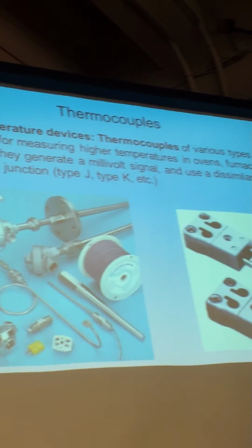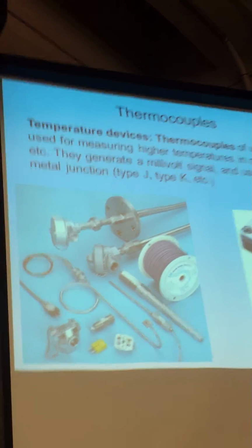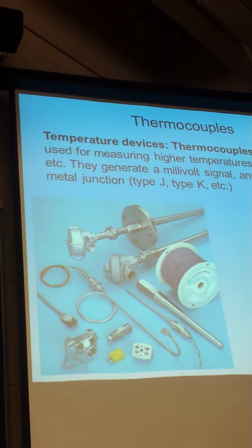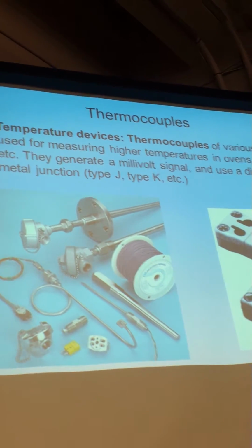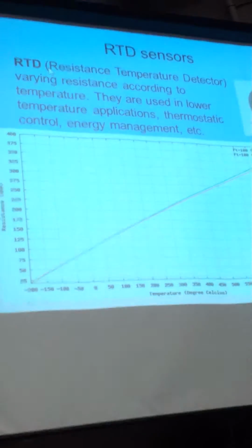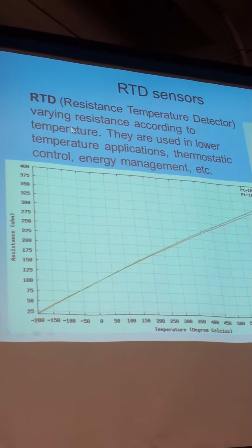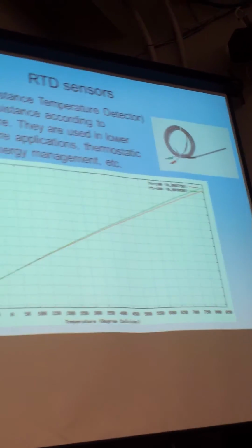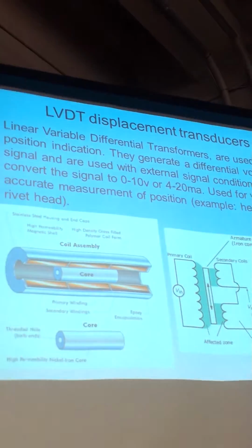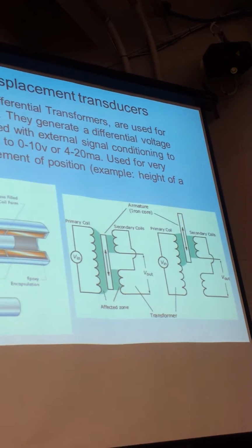Thermocouples. Okay, so we're going to go through a few of the devices. I will need you to remember that it's used for higher temperature applications. So for furnaces, anything with high heat. Know what RTD stands for? And how it varies its resistance according to the temperature. Know what LVDT stands for, because that might be a question.